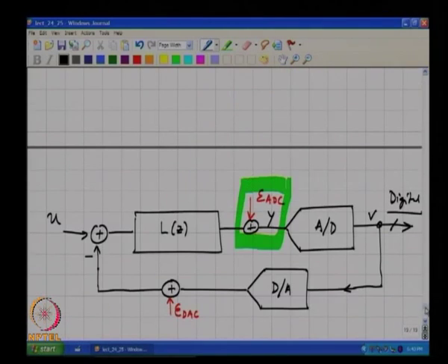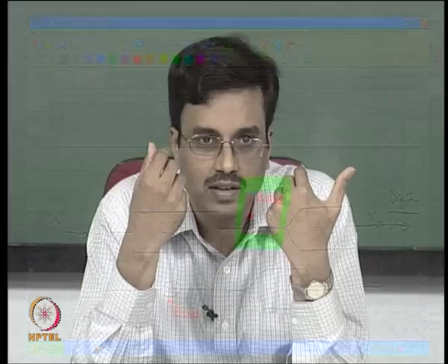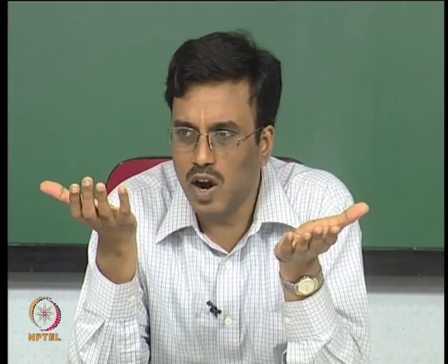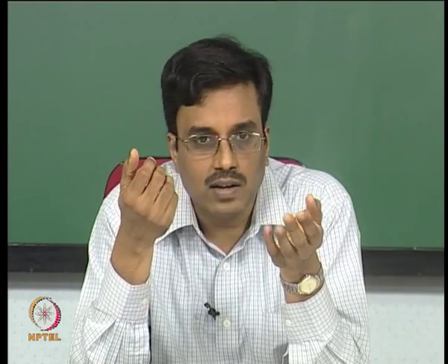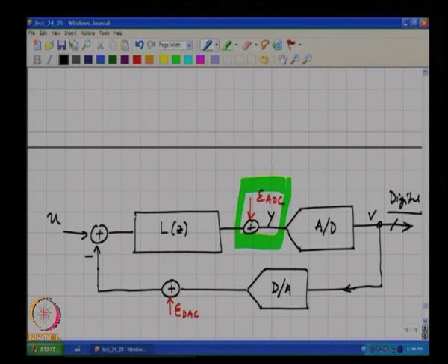So, great. So, you can see that in any case, I mean you can think about it this way, the output of the loop filter is being quantized, right. So, we are anyway going to add a lot of quantization noise to the output of the loop filter. So, in principle corrupting the thresholds by a little bit should in principle not matter too much. Another way of thinking about it is that the quantization noise is also being added at the same point.